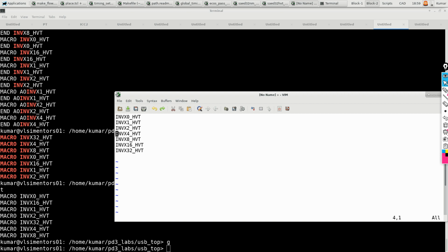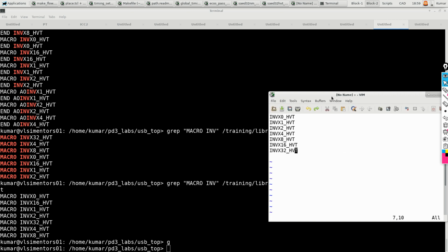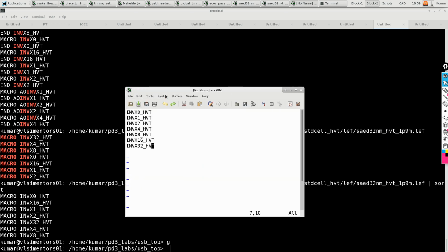But functional ECO means you have implemented a design, and it is ready for tape out in the next 2 weeks or so. Now the change that goes in is what we call a functional ECO, where you go and change or update your functionality. We will talk about all that when we get into the sign off stages, Mustafa. Is that okay?